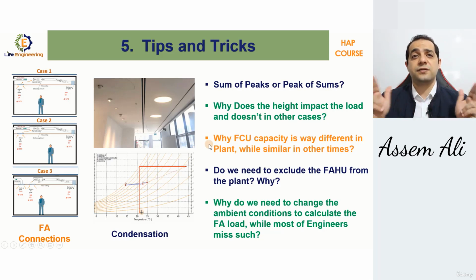Yes, such vast variance. Why in some cases we may change the height of the space up to 5 times or even more with no impact on the results. On the other hand, this can dramatically impact the load. Also, why the weather conditions of the projects are suitable for sizing all equipment except the FAHUs, which require in some cases changing the entire weather condition to calculate them only, and many other things.